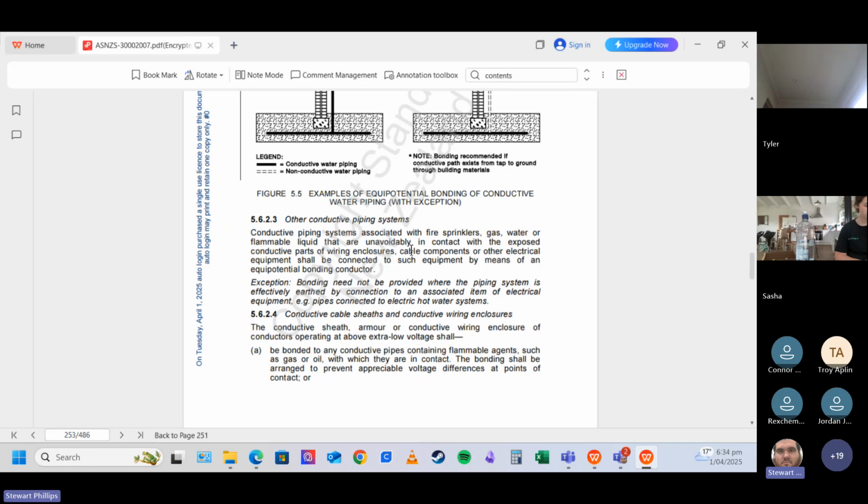Or, for example, we have a gas stove that has electric ignition. It's connected to our wiring system, we need to bond it. And just having the, say, if it's a 2.5 inside of a 6 mil conductor for that ignition, that 2.5 is not big enough for the bonding. So we need to run an extra bonding conductor.